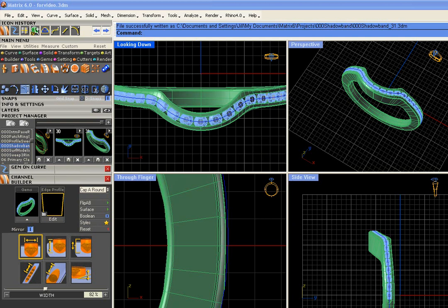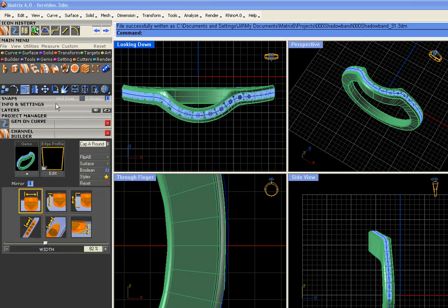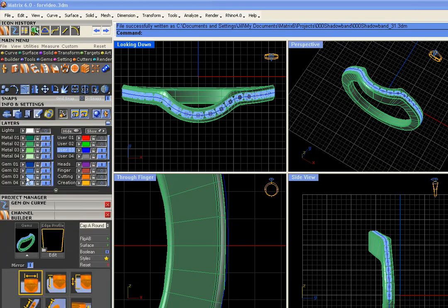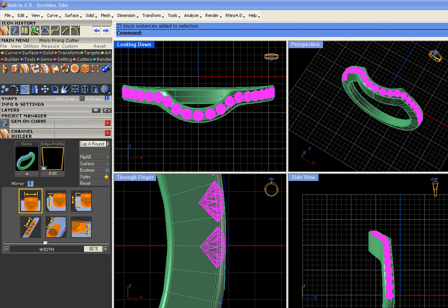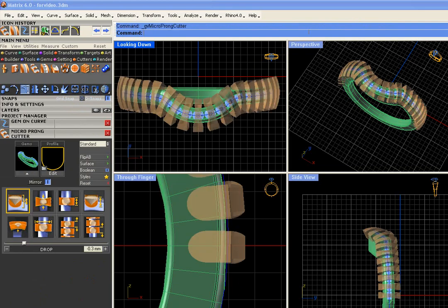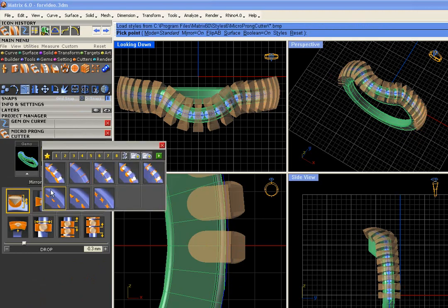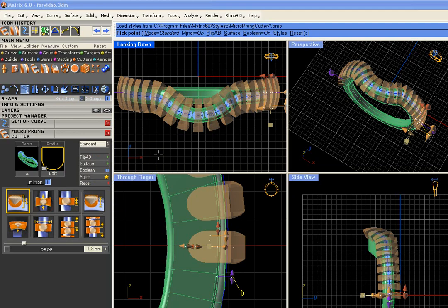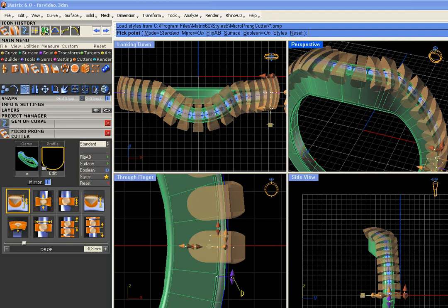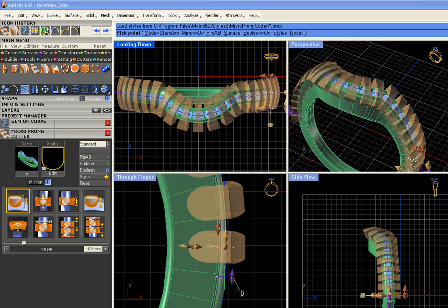All right, the last thing is going to be to apply micro prong cutters to this. So reselect the gems, come into the micro prong cutter tool. And this is from a style right out of the builder. And if you want to see that style, you go into the styles menu. It's this guy right here and hit apply. Okay. This also has the Boolean option, so you can tweak these handles if you don't like the results yet.